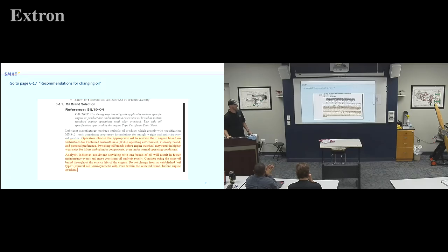Yeah, so you get a little bit of a mixed signal on some of these, but the main point is you should be very wary of switching around. That can be tricky if you land at an FBO and they don't have your brand of oil. What do I do? Do I run it low on oil, or do I add the wrong brand? You know, but just know it's a bad thing. Shame on you for switching oil. And beyond that, just try to avoid it.